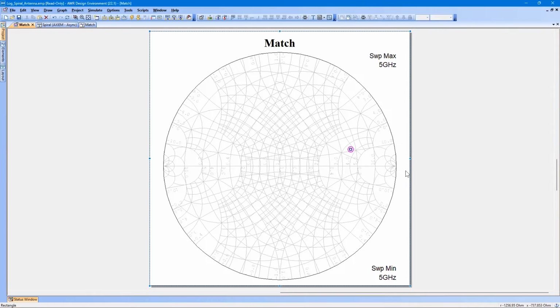And we can now see a perfect mirror of the impedance circles. So here are the smaller circles, and as we go to the right, the admittance circles are getting larger. And these are the circles that the capacitor moves on. Inductor on these circles, capacitor on these circles.